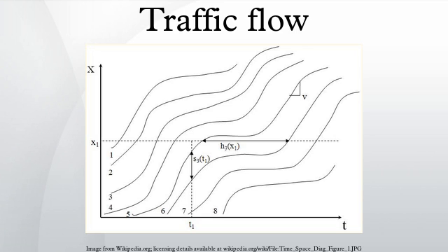If the operator wants the freeway not to be congested, the operator can impose the congestion toll, E0 minus E1, which is the difference between the externality of the freeway and the alternative route. In this situation, the freeway will maintain free flow speed, however the alternative route will be extremely congested.